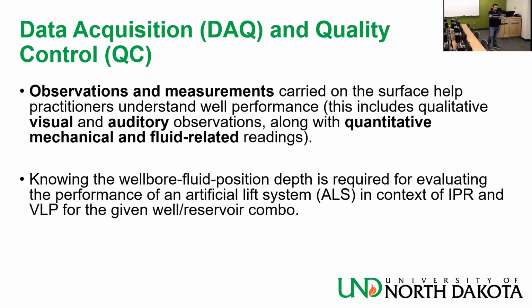Like if the well is idle, not moving, where is the fluid level? Where does the liquid begin? And you are going to use sonic for that. You are going to shoot sound signals downhole and see how fast they come back. And then divide the time by 2, divide by the speed of sound under those conditions, and you get the fluid level.